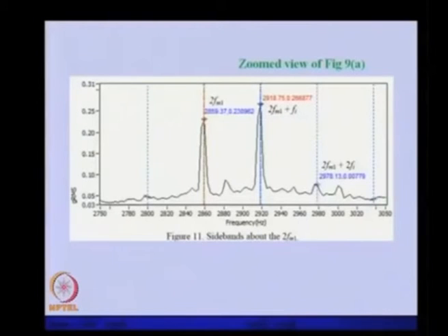This is another zoom view of the same figure. In this you can see additionally we have FM1, which is in the higher range we have shown here, and there is a sideband. So the sideband is more predominant than the actual first tooth missing frequency. So here it has been modulated. Even this is the higher harmonic of the tooth missing frequency, the second harmonic of the tooth missing frequency, and the sideband of that. Here also there are higher sidebands, twice the speed of the shaft.